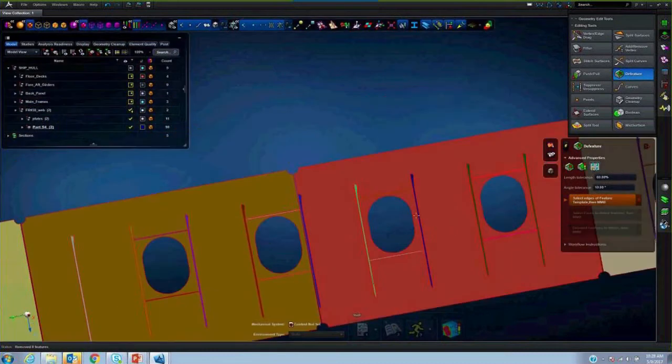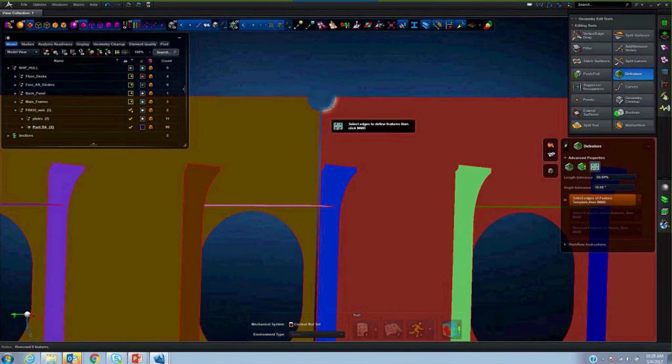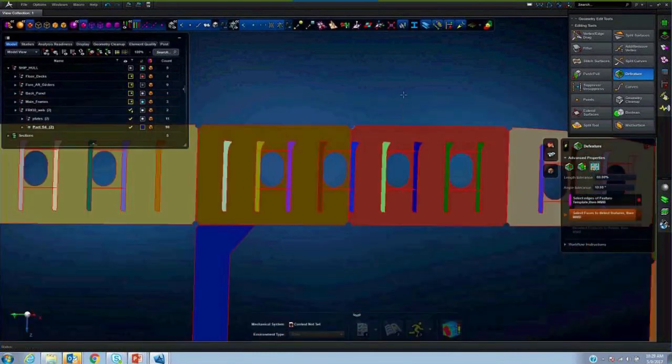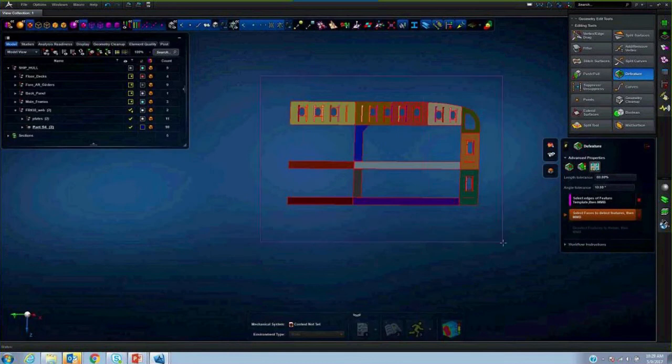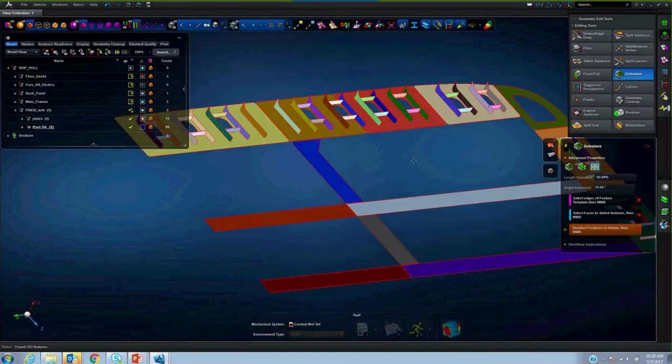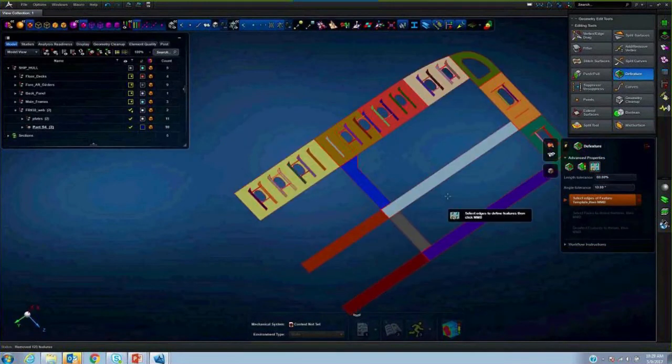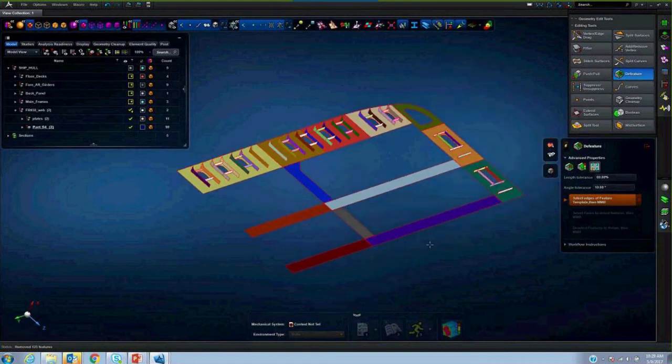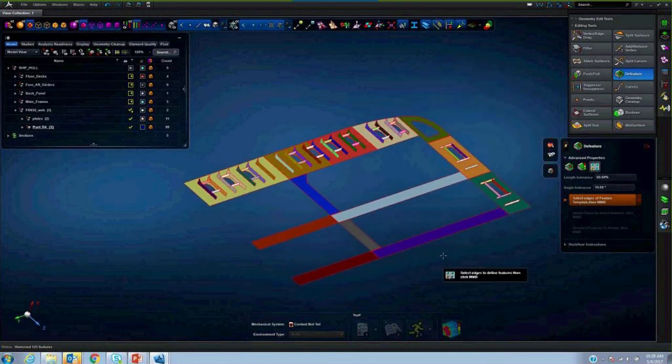And in this model, there could be standard features as well, and such as this fillet. And can this tool work on these standard features also? Let's select one of them, and let's identify how many of them are there in this model. And there are 123 features that identified the fillets in this model, and now you can say go on defeature. So now it's as simple as passing through these techniques to really defeature that one, to remove the unwanted geometry that is not suitable for creating the meshed model.